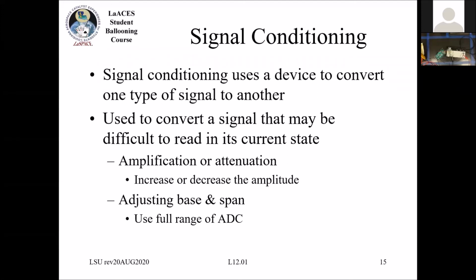So there are a few tricks that we can do to make the most of our resolution. A lot of times it's easier to change the signal going into the ADC than change the resolution of the ADC. So we do something called signal conditioning.